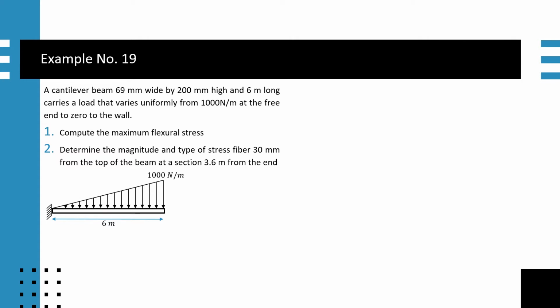So, sa number 2 naman, determine the magnitude and type of stress at the fiber 30 millimeters from the top. So, 200 millimeters high kasi yan. So, ang hinahanapan natin is yung 30 millimeters from the top. So, bababa ka ng 30 millimeters. And that is 3.6 from the end. Yan. So, i-explain natin lalo yan kapag bibigyan na natin ng illustration.